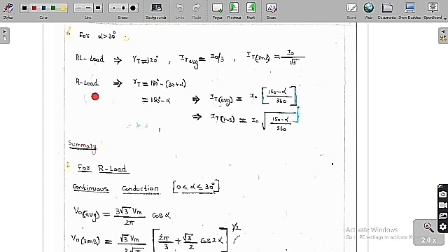Whereas for R load only, I have already told you, discontinuous conduction mode is possible for alpha greater than 30 degree. Therefore, when alpha is greater than 30 degree, discontinuous conduction mode is only possible for R load. The thyristor is going to conduct only from 30 plus alpha to 180. Only for this range it is going to conduct. So 180 minus of 30 plus alpha gives 150 minus alpha. This is the conduction angle of each thyristor, 150 minus alpha, when alpha is greater than 30 degree, only for resistive load.